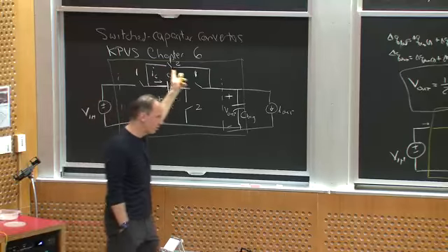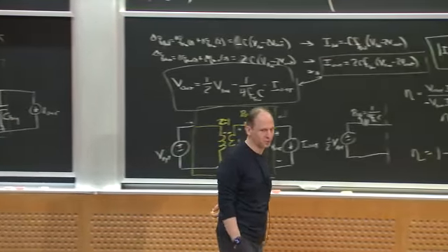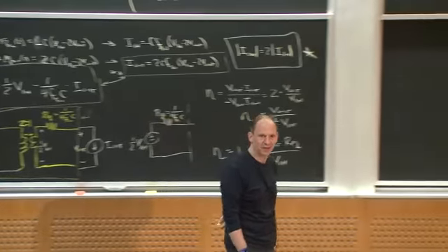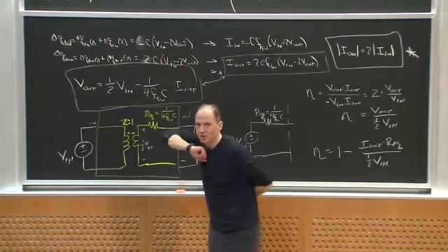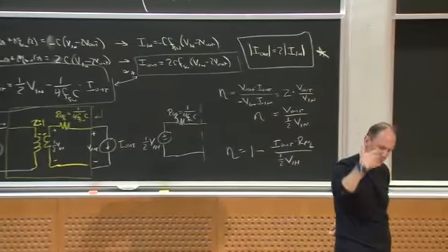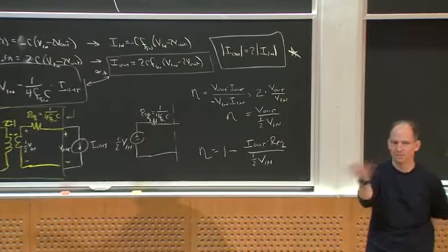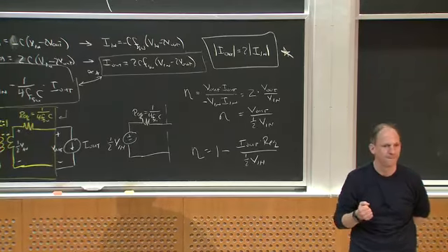Now, it doesn't matter. You notice the switch resistance isn't even in here anywhere. It doesn't really matter what the switch resistance is, okay? The only constraint I have is that I have to finish charging and discharging, okay? And that's just because, you can do this by basically charge methods to find out the efficiency.